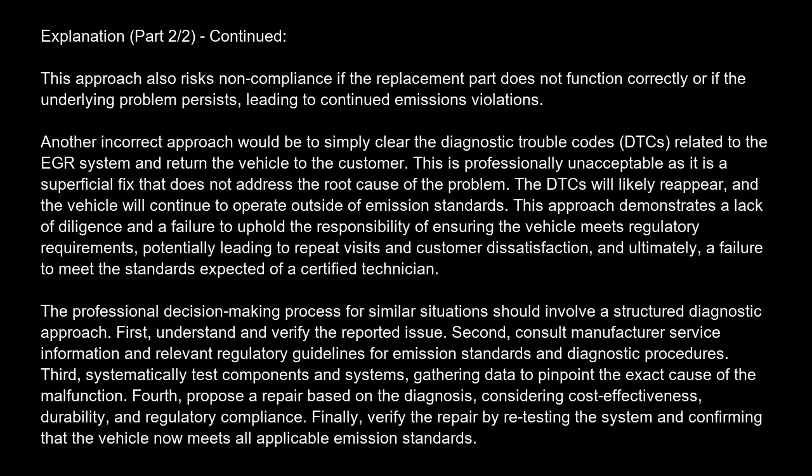Fourth, propose a repair based on the diagnosis, considering cost-effectiveness, durability, and regulatory compliance. Finally, verify the repair by retesting the system and confirming that the vehicle now meets all applicable emission standards.